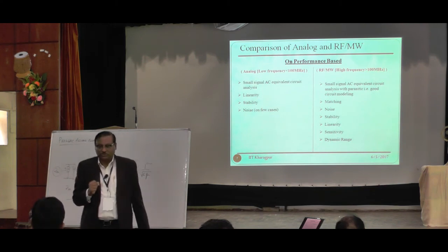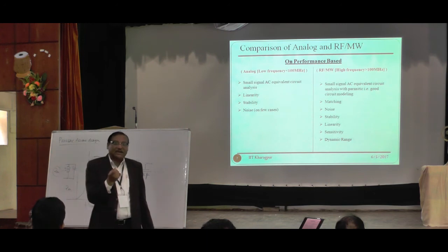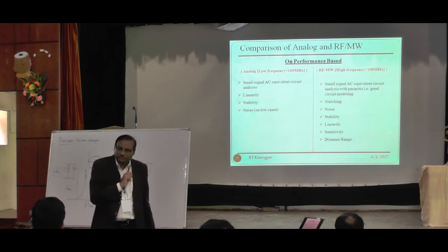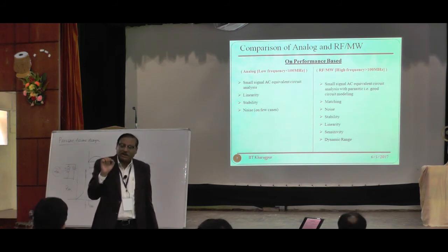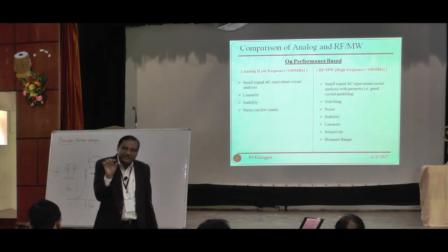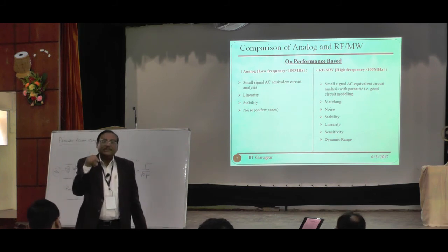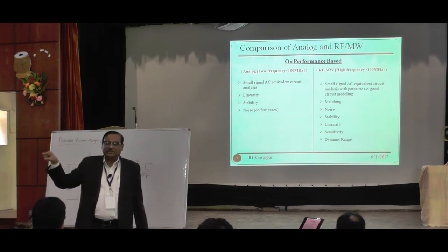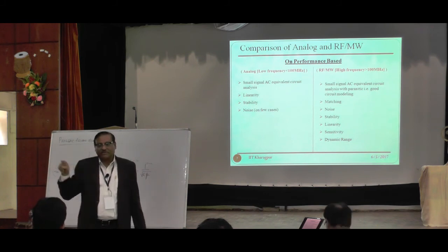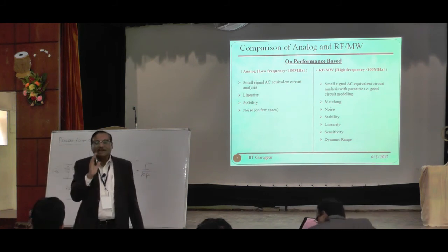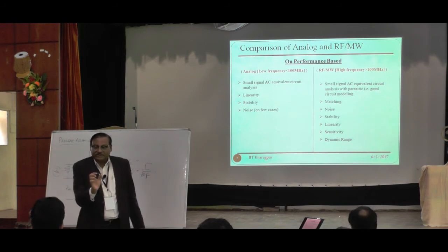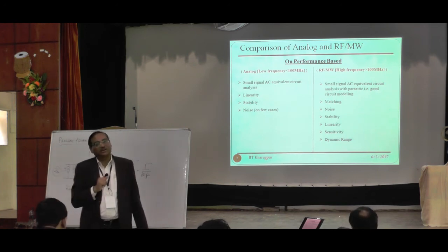Suppose I am giving 1.2 volt quiescent voltage, and I am varying the input signal in microvolts. Think of it, within that quiescent point the variation is a few microvolts, 100 microvolts. Then that is called piecewise linearization. So I do not consider any nonlinearity within that small part of the exponential zone. Mathematically, e to the power x is 1 plus x plus x squared by factorial 2, plus x cubed by factorial 3, and so on. Introducing linearity means I am actually negating all those second order and third order terms.